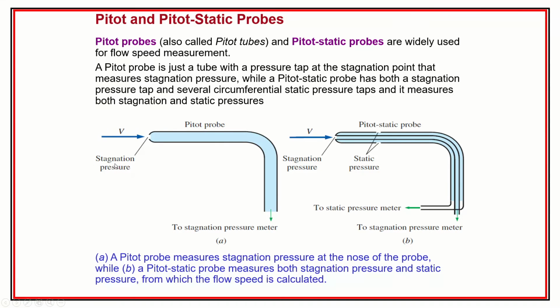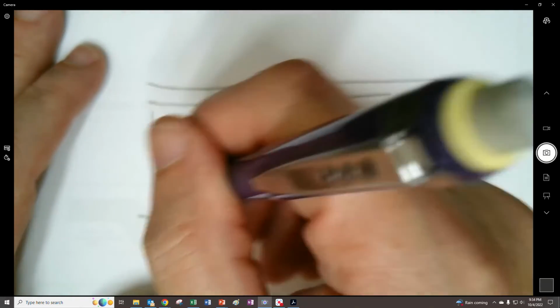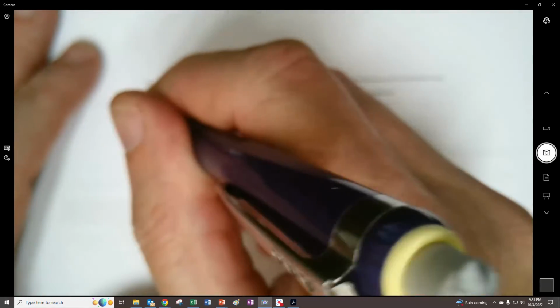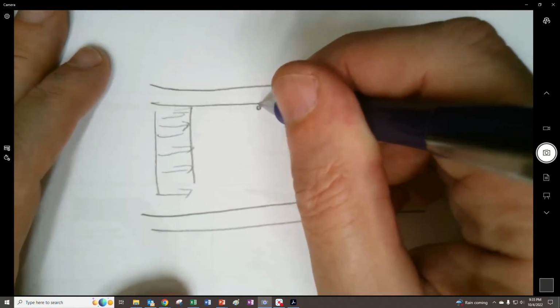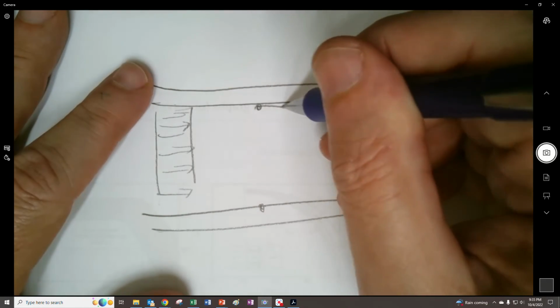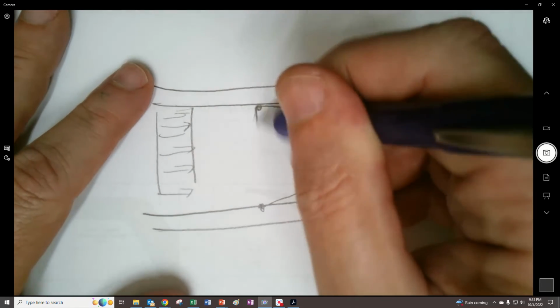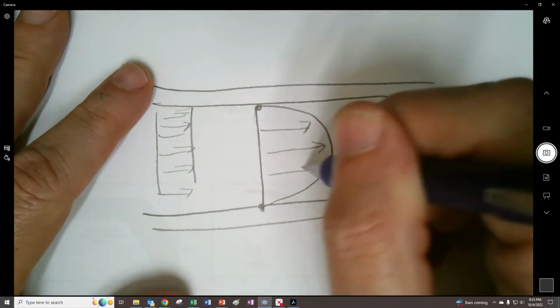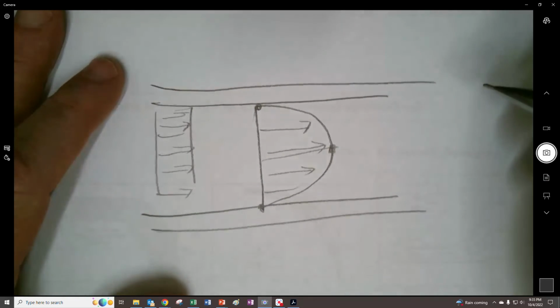The reason why pitot tubes aren't a great measurement for flow is because they really are good for measuring local velocity. And as you'll recall from the first class of the semester, when you're in a pipe and you have a velocity flowing through here, we think of it as being uniform across here, but we have that idea of the zero slip location. So we actually have a developed velocity profile that's distributed like this, where the velocity in the center is going to be larger, right?